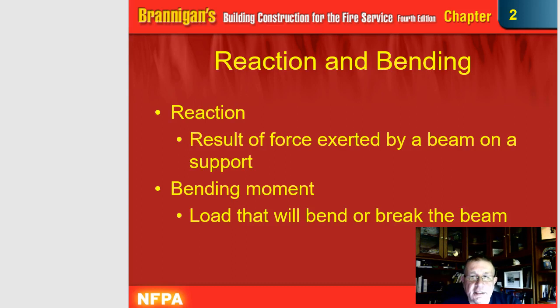The other thing is reaction and bending. It's all part under heat. One of the biggest fires that I had years ago was the Carousel Inn on Reading Road. It wasn't the first fire we had, it was the second, actually the third fire we had there. And this was in the back part of the building where we actually seen I-beams that were probably 24, 25-foot spans, and they're probably every bit of, I would say, 24 inches in a span width as far as the thickness goes. And we watched under heat conditions how those things twisted like pretzels under heat conditions.